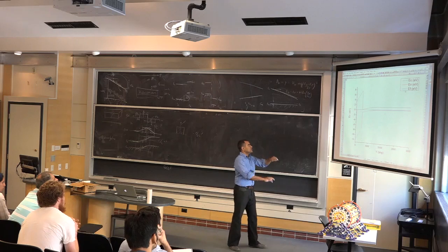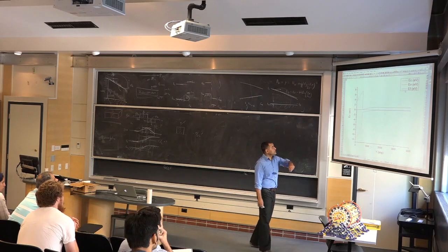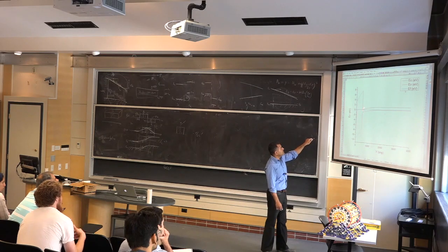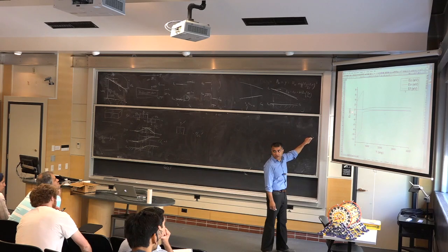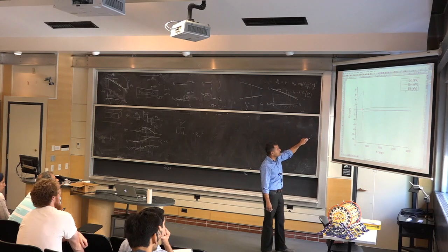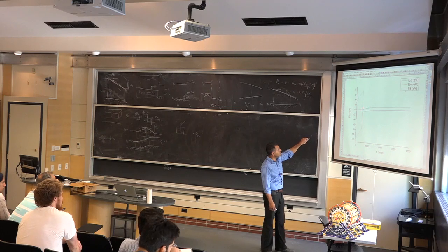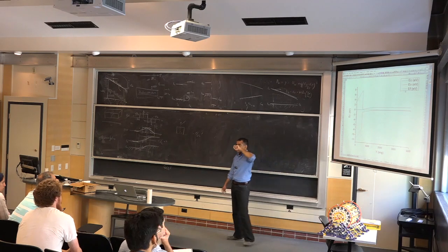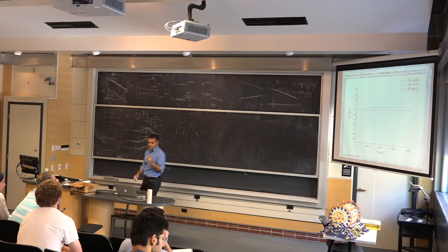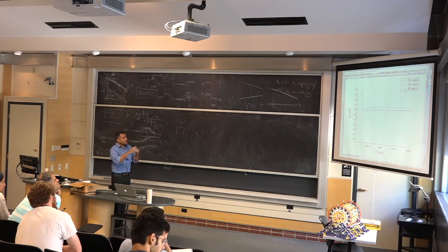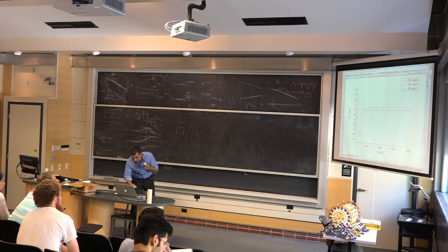And we're going to discuss that in quite some detail in the next class about how the charge here depends on the voltage you apply here. But it calculates the whole thing. You can see here, if you zoom in, there's a little triangular quantum well. That's where your inversion channel of a transistor forms. It's a 2D electron gas, and so there's some quantum aspect to it, and this program actually calculates all that stuff self-consistently.